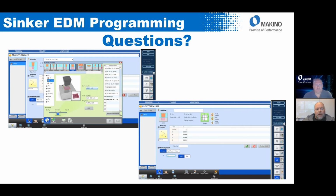We had talked about the drop downs and the roughness area, basically what surface finish we want. So if we programmed, let's say, a 5R max finish, I may only get a 6R max finish because I've taken some of that stock away, and that EDM crater that's created may not clean up. So there's always risk with sliding towards the speed side, but understanding what that's going to do and how it adjusts the surface finish is key.